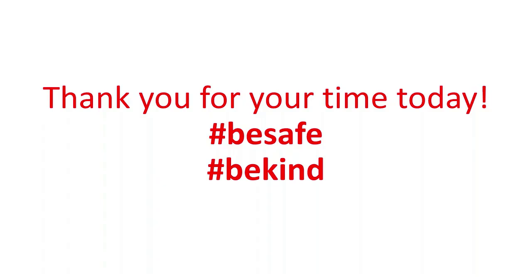And the technology there, again, you've got a very similar interface when you're drafting, things like your crossing selections, your window selections, your right-click functionality, your object snaps, everything's the same. The only difference in the web app is it uses the simplex font when you place text, and that's to provide optimum functionality within a browser. Because if you had all those different fonts to think about, the browser has to think about that, and it would slow the AutoCAD web app down. But it's a great piece of functionality.